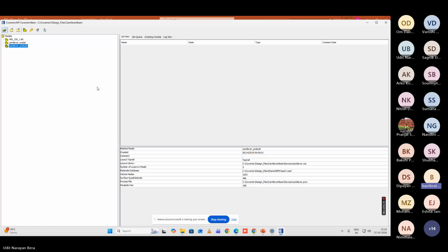That is not possible, or that is not feasible also. Unnecessarily that will waste my time, resource, effort, everything. From an economic point of view also it will be violated. So that's why first we will be doing everything in the simulation. And for simulating, first you need to choose what your dimensions should be. You have to have some idea of the length, width, thickness, and the geometry of the structure. Then what material I essentially require to design it, whether I should go for silicon or aluminum or some other metal. So I need to know the metal.